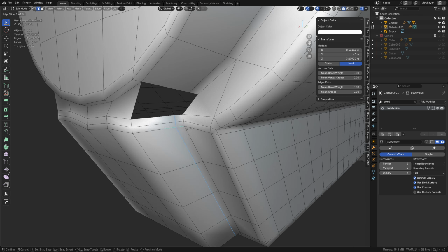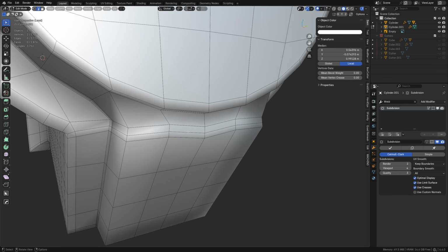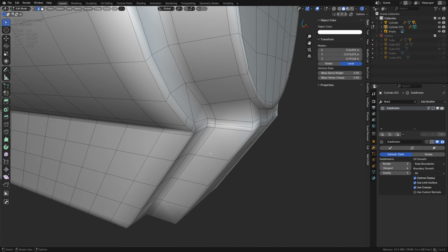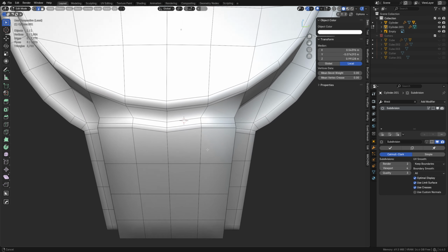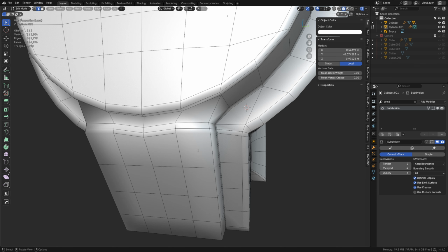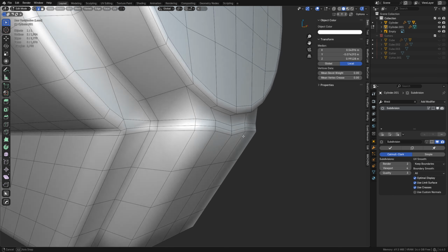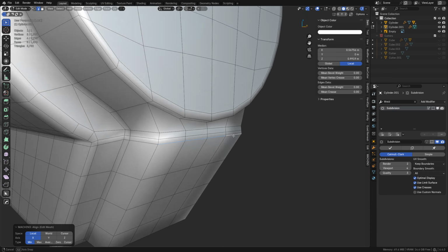Like you need to go through sometimes and do that first, and then try a subdivision or a quad mesh that you can subdivide, right? And if you fail at doing it one way, try doing it a little bit different and maybe start it over. You might even have to redo your block out, because you don't always get it right, right? You might have used the wrong segment counts. You might have run the topology wrong or destroyed something by accident during the process of creating something. It happens. You get used to it. You just redo it real quick and just keep moving.